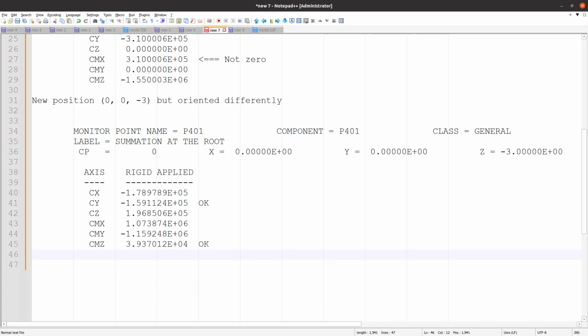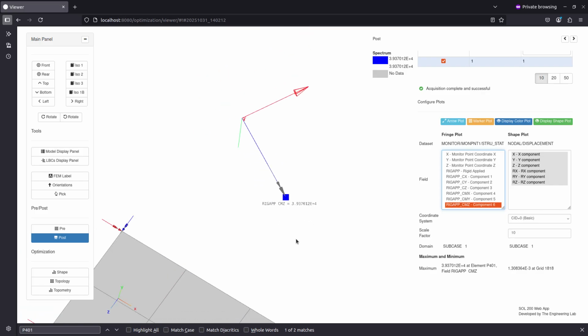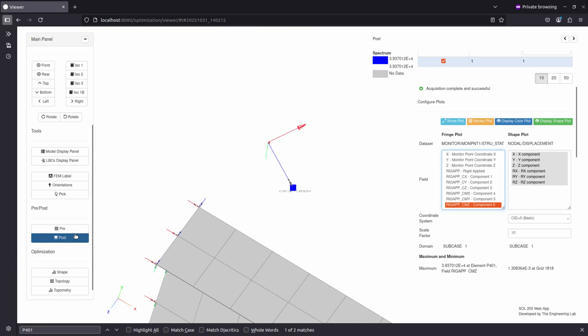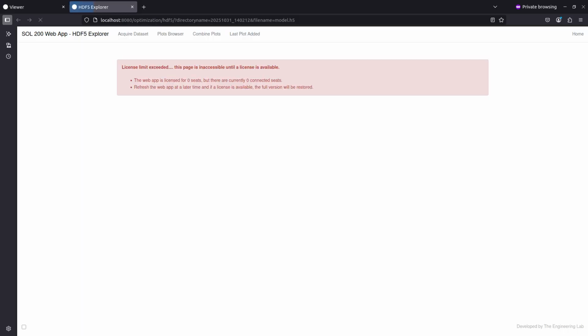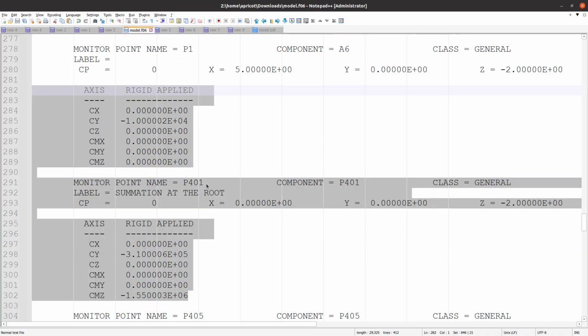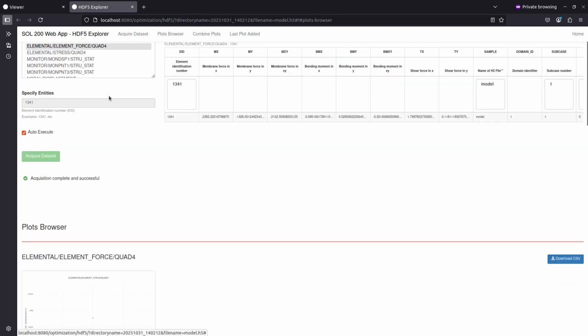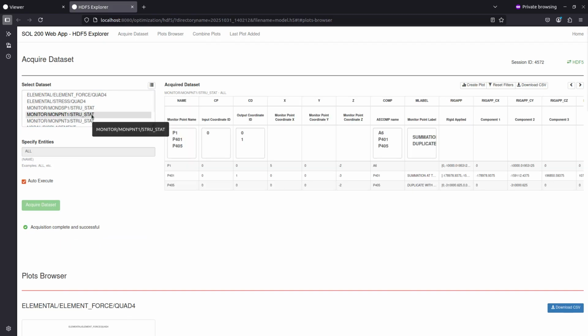Great. So thankfully, even though there was previously a bug, I found a way to quickly fix it. We were able to continue this tutorial. Okay, now like before, you need this data out to a CSV file. The goal, and I encourage anyone who is scripting, who's learning how to use Python, any developer, try to avoid reading the F06 file as much as possible. If you do rely on the F06 file, in 1 or 2 years, you'll find out that the script breaks again and you have to rewrite it. Here, that's okay. We use the H5 file to get that data.